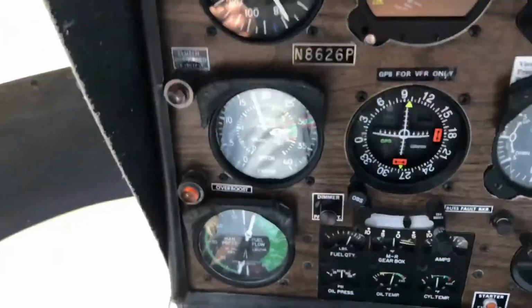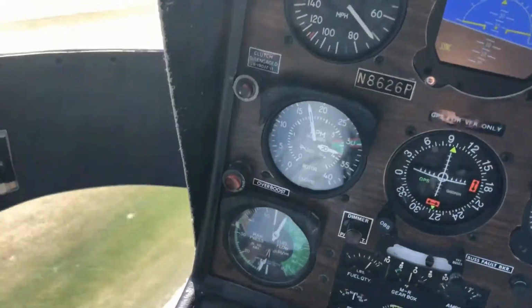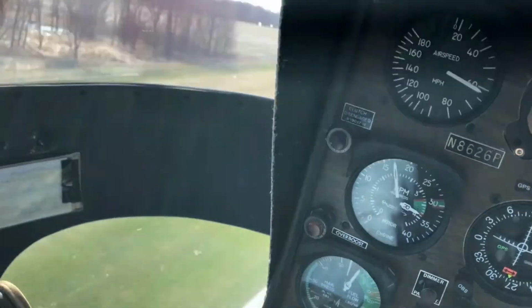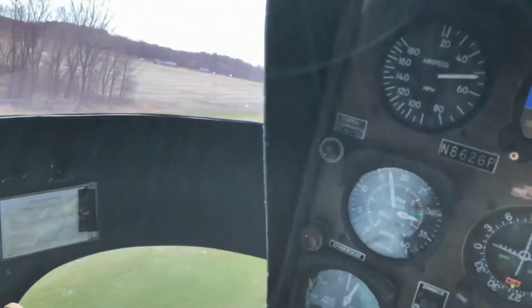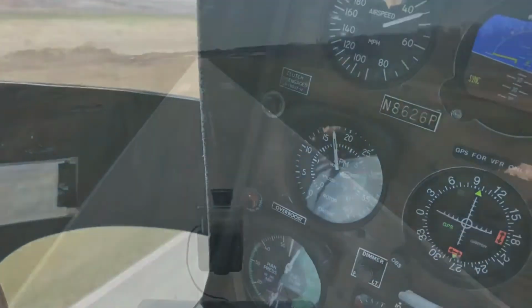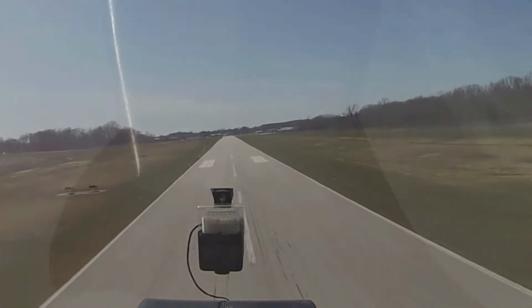He's getting ready to start the flare. And as he flares, it rises even higher, so he's going to have to raise collective to keep it from going too high. Now he's leveling out the helicopter, bringing the throttle back in.